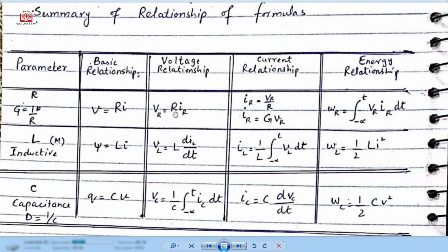I know that V is equal to IR or I is equal to V over R. This is the first one that you maybe already memorized. So these four blocks, the voltage and current of the inductive circuit, and the voltage and current of the capacitive circuit, are really difficult to memorize, but I am giving you a very basic trick that each and every block is the inverse of the others. Like here, if you just memorize this term, V is equal to L di over dt.